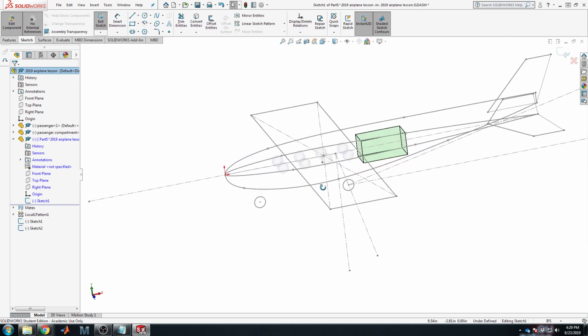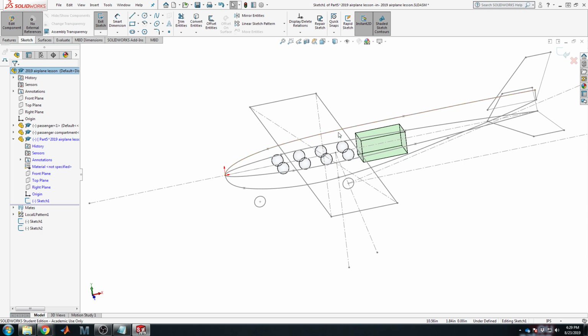Because that means as you're working, you can't accidentally reference something to this wireframe sketch we had before. It sounds like a good idea until you think that everything on the plane might be slaved back to that. And if one of the linkages breaks, which SolidWorks admittedly is not the best at maintaining, if something moves too much and it's displaced an inch from where SolidWorks thinks it should be, it sometimes will just break the link, and then that could break your entire airplane. So I want to have all of these sketches we're making here independent of one another. So leave that on. We're editing a component inside of an assembly, which means an actual individual part. There'll be no external references placed there.